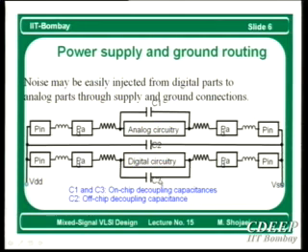So if I don't have C1 and C3, I will have a noisy and in fact all the time switching VDD and VSS for the digital circuit, which is not recommended. And it may even happen for analog if I have a lot of high power modules in the analog part. So what do we do? We should have two big capacitances on chip, which are called decoupling capacitances.